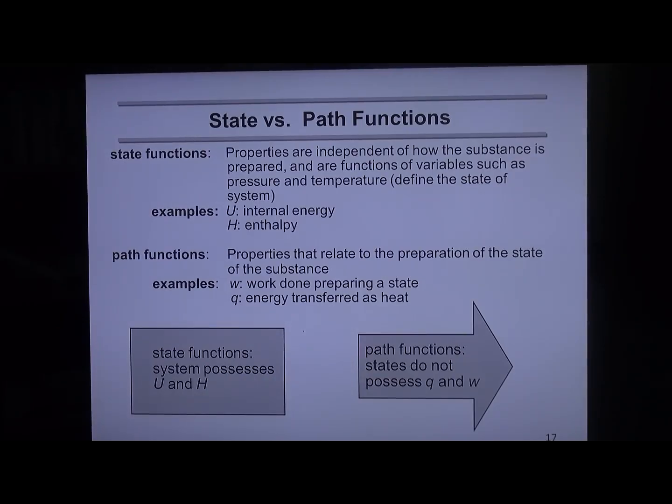You remember that depending on the processes, free expansion, isothermal reversible expansion, adiabatic expansion, etc., the amount of work and the amount of heat were different, right? That shows why these two functions are path functions. On the other hand, internal energy and enthalpy, if the initial and final states are the same, these properties are the same.